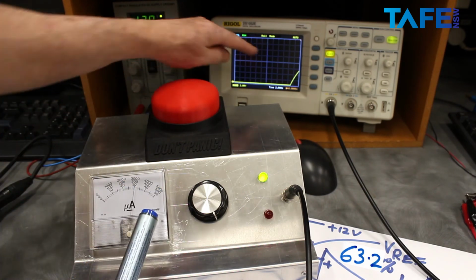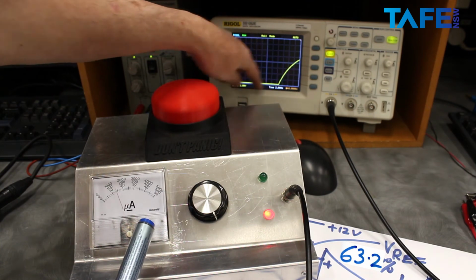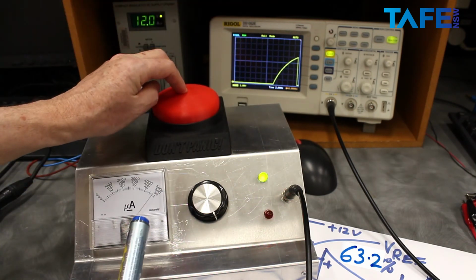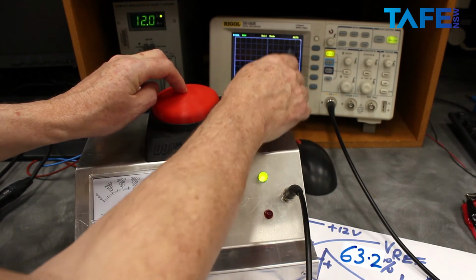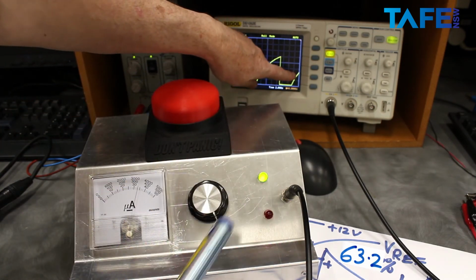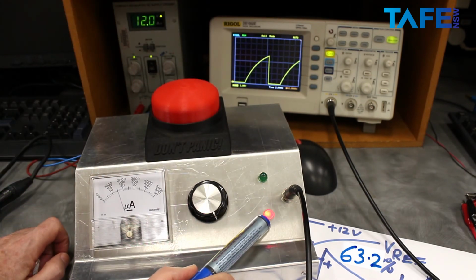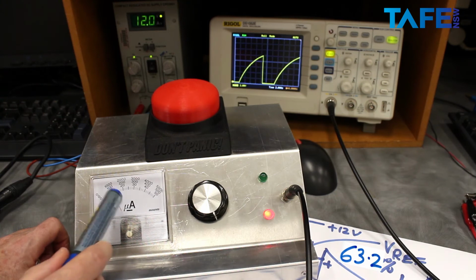Charging current dropping. Oh, there we are, 2, 4. It looked like 4.5 volts. That's on 2 volts per division. Let's do it again. You can see there, drop down to 0. It's about to charge, charging to about 5.8 volts. The state changed because of the threshold I had set.